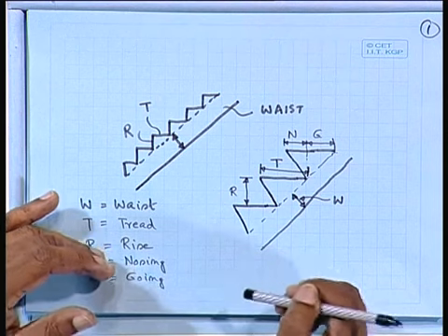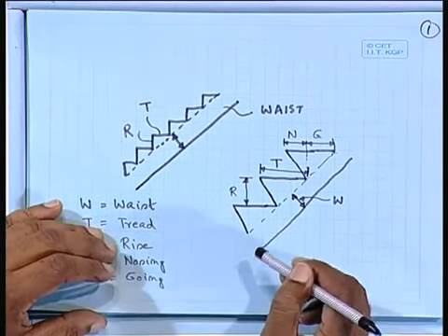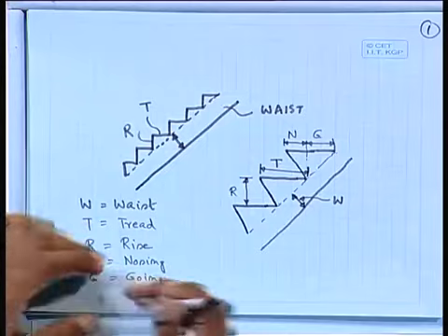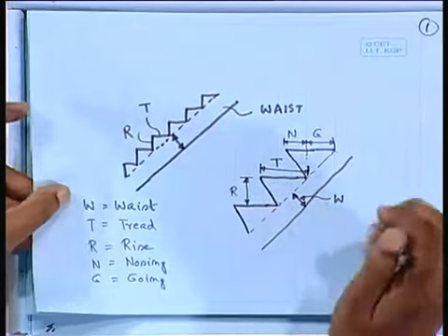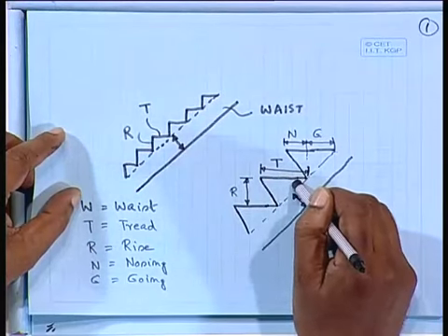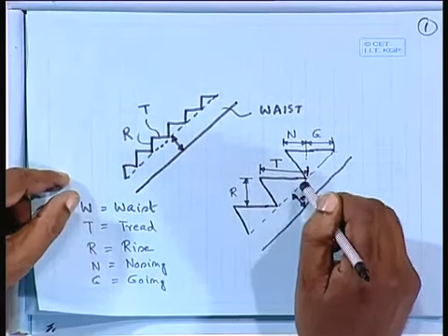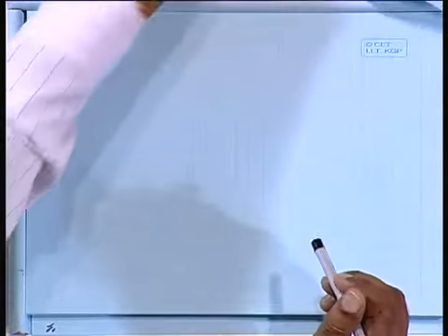Also, compared to the general load on rooms, a balcony may be crowded more. Similarly, the staircase also has a frequent chance of being crowded. That is why this load is more compared to the standard load on the rooms. So the first thing is the dimension of the rise and tread, and the second is the loading. These two things you have to consider in our calculation.